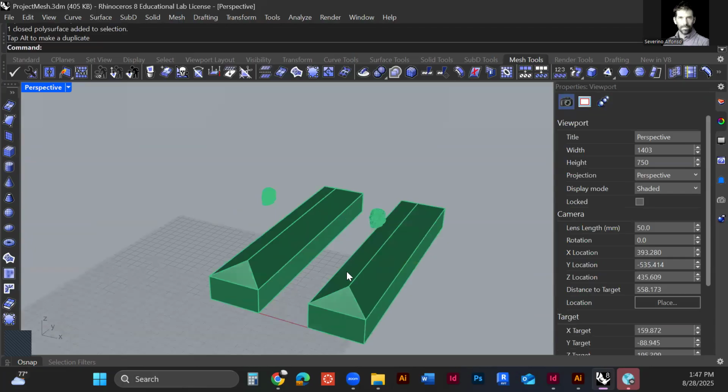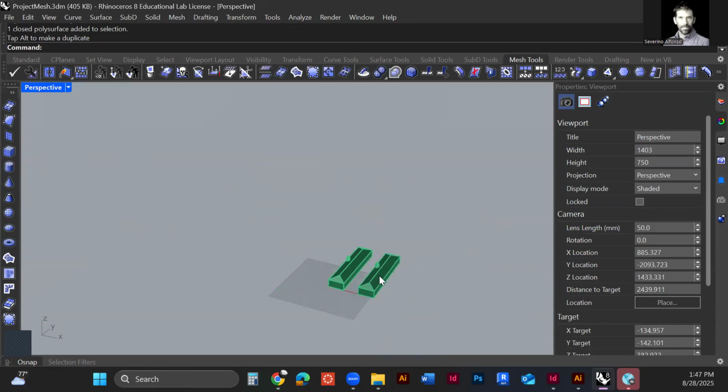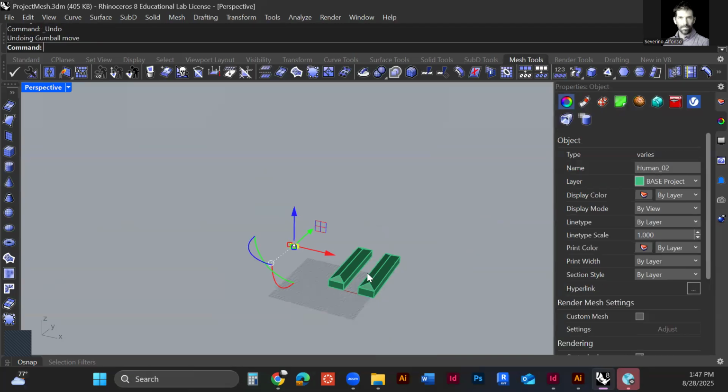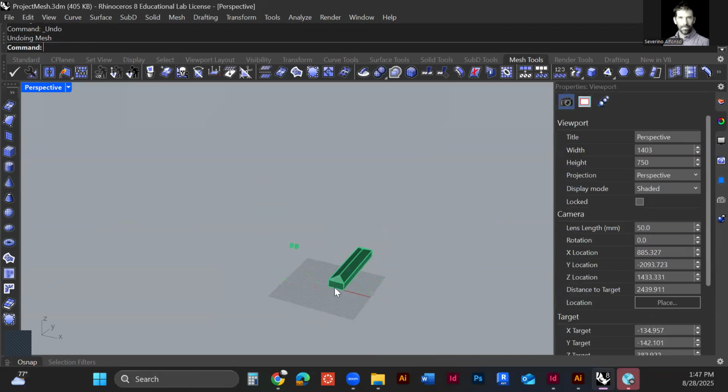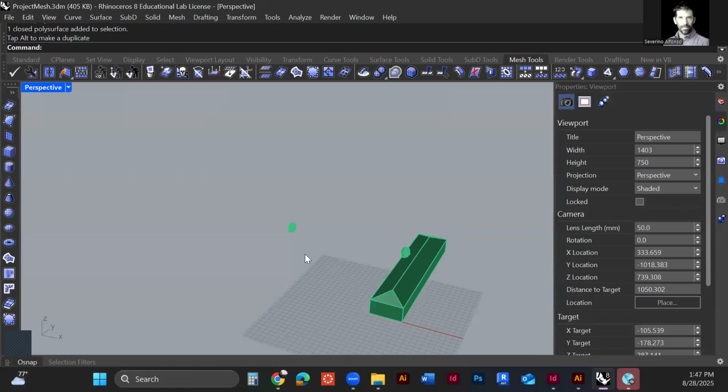Is there one I recommend the most? I probably recommend going the surface line. So I recommend that you transform the mesh to NURBs and do a Boolean operation using NURBs. So I'm just going to do that. This is a polysurface. This is also a polysurface. I'm going to use this too. Okay.